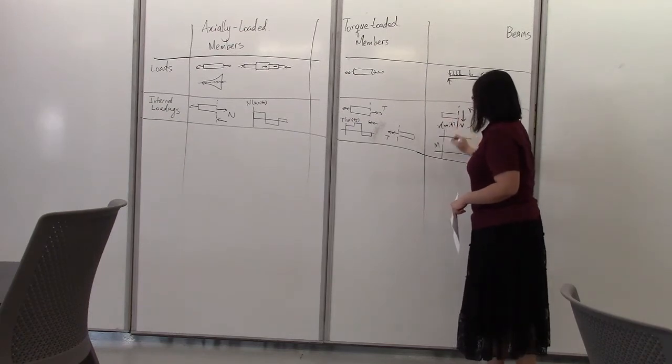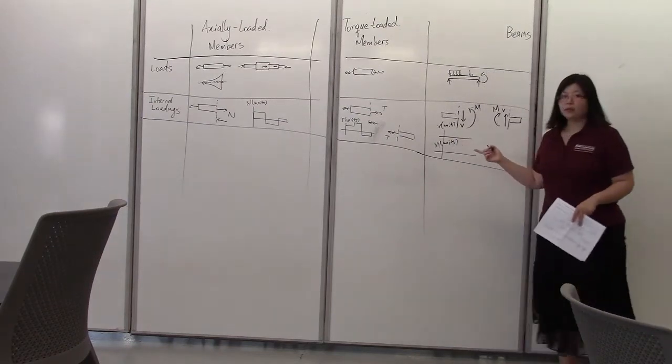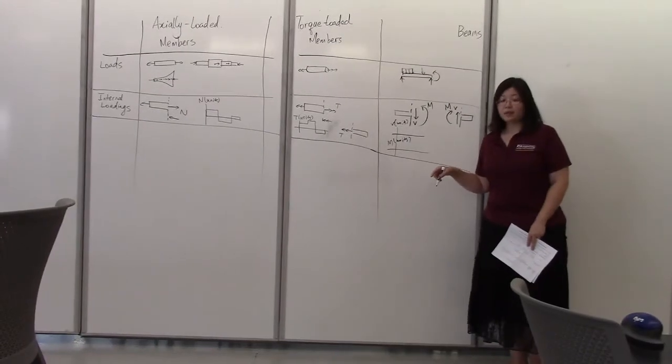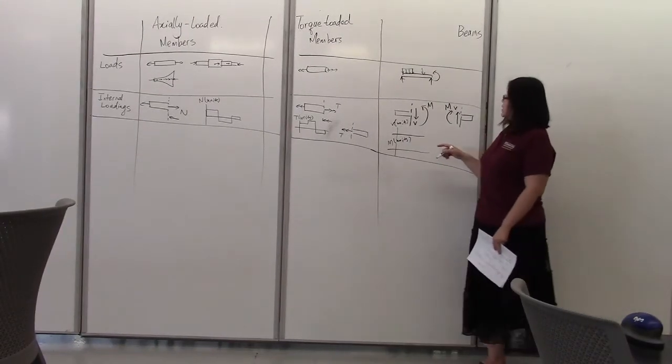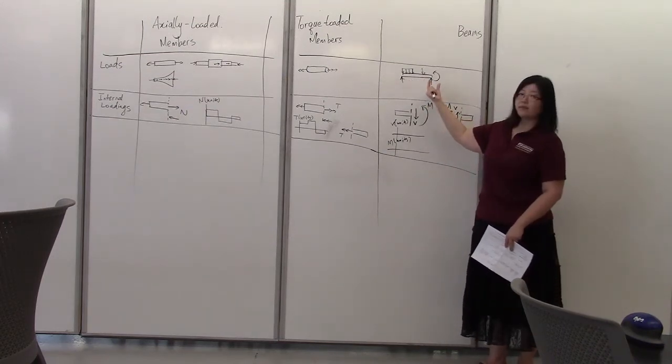Again, we have units and units labeled. Now this could be created using two different methods. We could either use the method of sections or we could use the graphical method. For the method of sections, same here, you would divide the beam into a few segments.